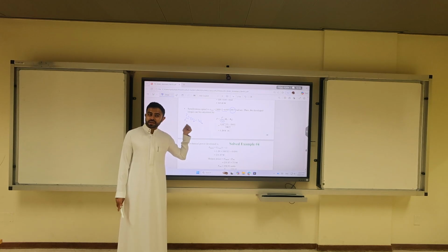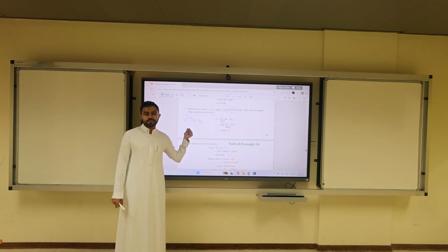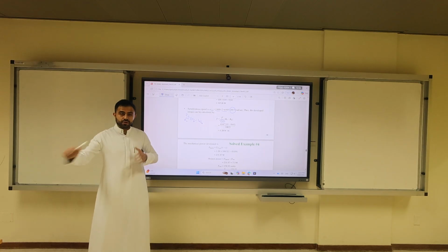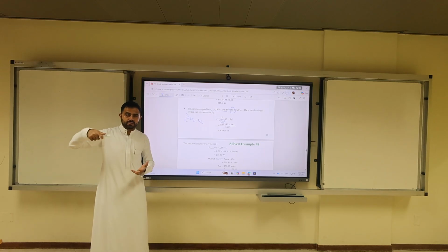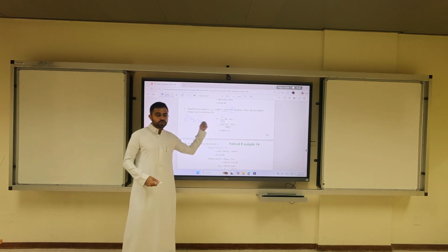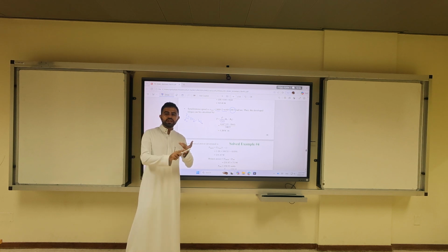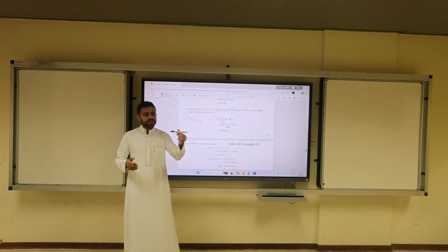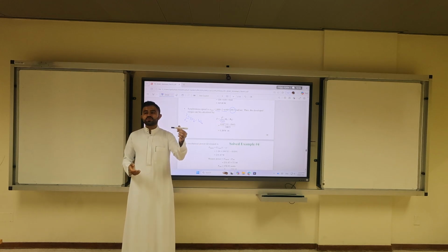Okay? This is one of the tricks where I want to test the A+ student. Okay? As a concept? Probably maybe in the exam. I think a generator is the opposite. For the generator, for a motor, yes. But for a generator, the mechanical input power is always larger. Because the difference would go into friction, windage, friction between the bearings, and any other mechanical constraints. One of them is, for example, the center of the inertia of the rotor has to be held during a rotation.